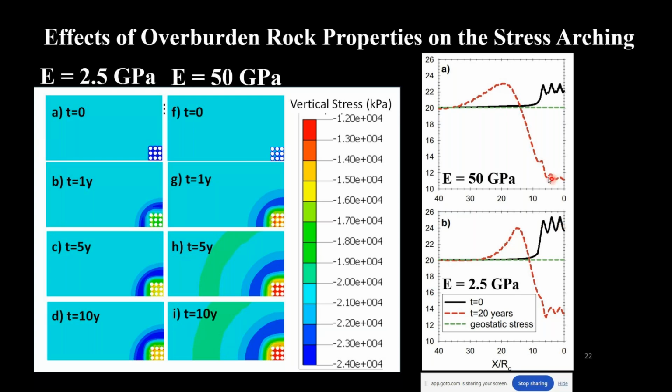And here, after 20 years, we see that the stresses are redistributed to a much larger area than for the weaker overburden rock. And also the stresses here, they are much smaller, right? It's only 12 megapascal, and here is about 14 megapascal.